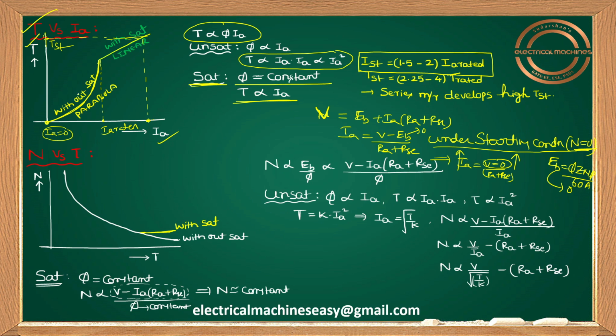Okay, guys, so please try to understand. Yes, definitely the series motor develops high starting torque. Therefore, wherever I need high starting torque, definitely there a DC series motor is preferable. If you take the example of traction applications, I told you just previously when I told you.